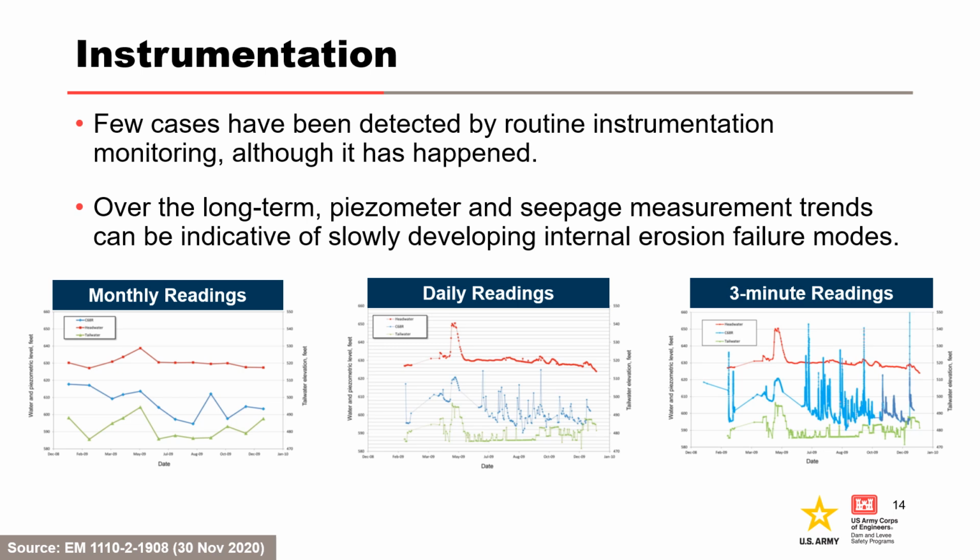For example, tailwater at a dam may change frequently and rapidly due to power generation or spillway operations. If a piezometer reading is taken only during low tailwater and the tailwater reading is taken only during high tailwater, the relationship between the two variables is obscured. Daily readings provide higher data resolution for a rapidly changing instrument. However, a daily interval is typically the highest practical frequency for instruments that are read manually.